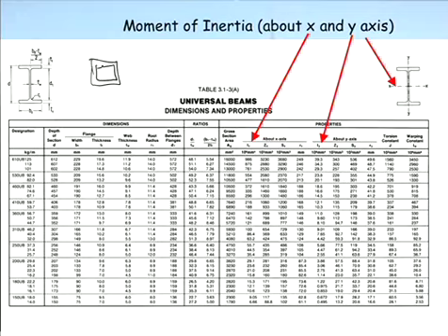this table now, the first column is the section size. So here it's a 350 UB92. In your tables, it's a 250 by 250 square hollow section by 3. So this dimension here represents the width, the depth of the beam. Now in this table, you can see a cross-sectional area column here. That tells you what the cross-section is for your section.